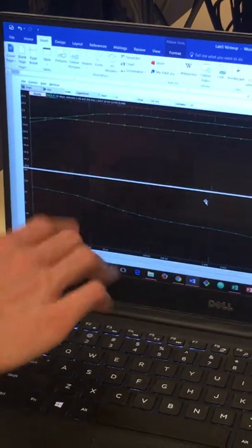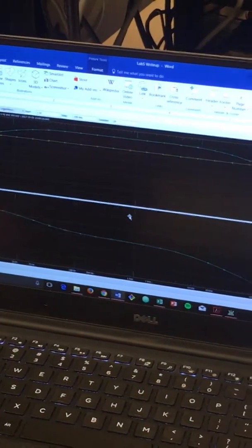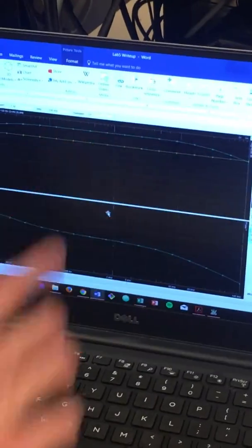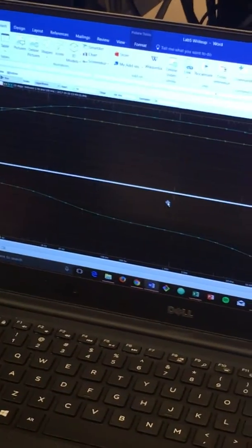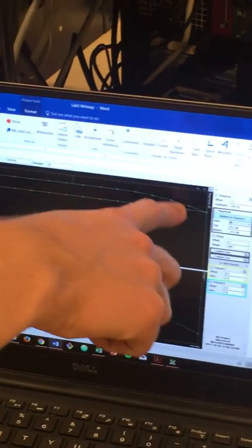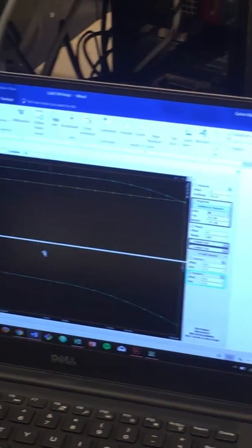So at low frequencies the signal is attenuated because the high pass filter does that. In the center, neither of them attenuates it, so you get all the gain, and this time the gain is multiplied. You multiply the gain of each circuit together, so the ratios that we had before are now multiplied. So we have a higher gain, and then the signal is attenuated at the end because of the low pass filter.